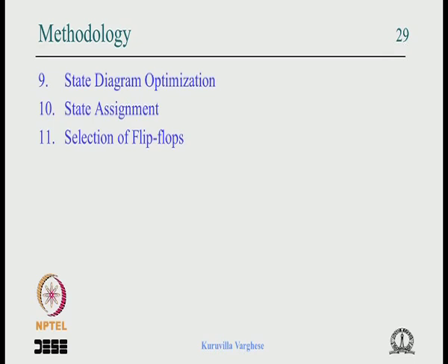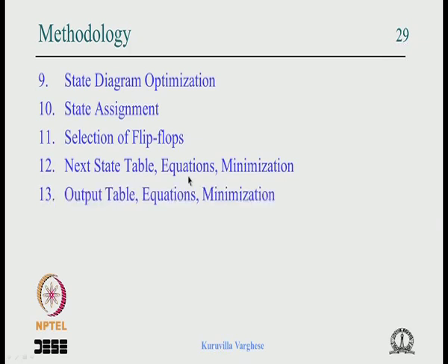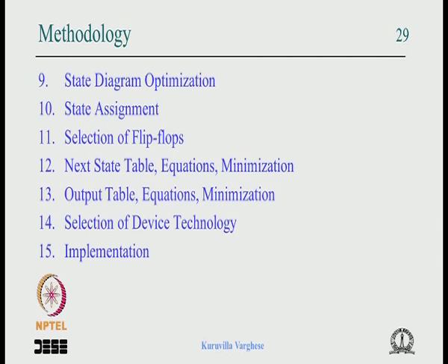We have to do the selection of flip flops, what type of flip flops are used. Then we have to develop the next state table depending on the flip flops, form the equation, minimize it, and do the output table equation and minimize it. Then ultimately we have to choose some device technology and implement it. Once implemented, things won't work at the beginning, you have to debug it.